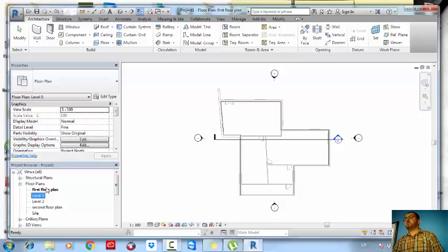Fine. So let's make sure that we all know the technique. We have to draw, then to modify. Fine. What am I drawing? I'm drawing objects. I'm using objects. What are these objects? These are the families, and then I am using or selecting the types. So if I'm drawing a wall, for example, am I drawing a concrete wall or a gypsum board wall? Fine. Or maybe a curtain wall.